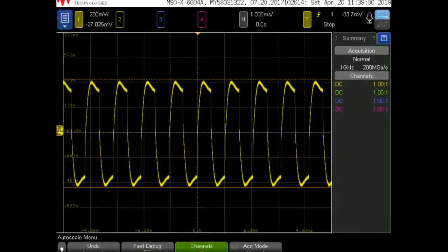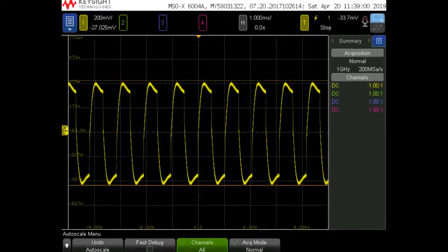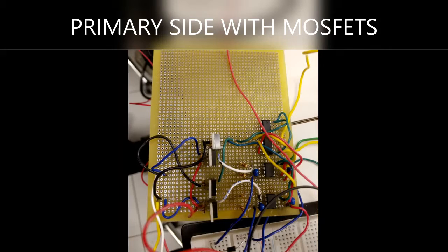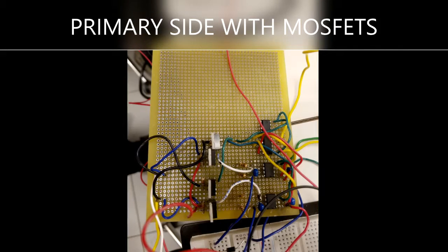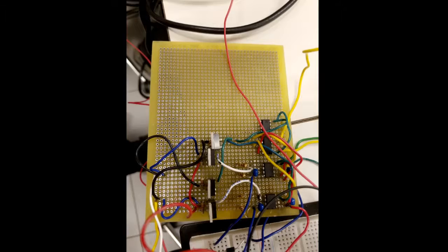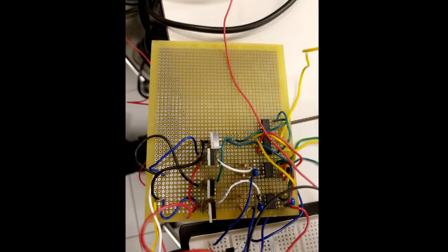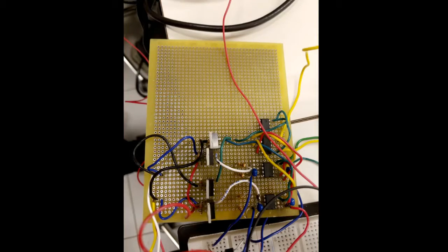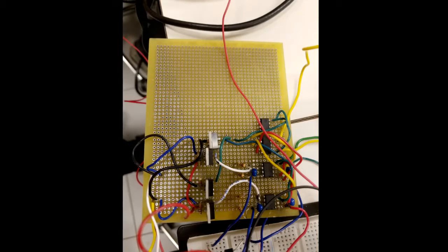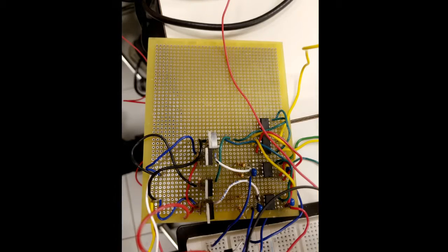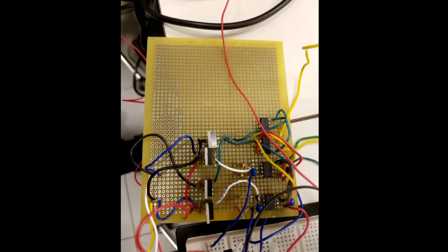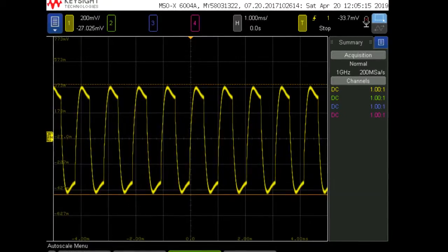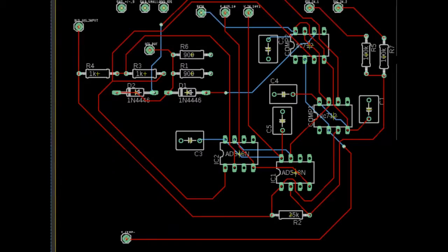The problems for the project really started appearing when we attempted to combine the primary and the secondary side. After many days of testing, we figured out that our problem was that our current source was non-ideal and therefore the thyristors had a delay when communicating with the FPGA board. This caused them to not respond, because improper commutation was not allowing them to be turned off, and then they were stuck on. This flaw proved to be fatal for the project, and we had to switch from thyristors to MOSFETs for the primary side to make sure they could turn off.